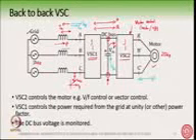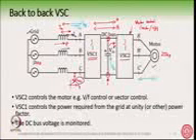So this current, the current which is drawn, this current IA, whatever direction you take, if you reverse the current, how will you reverse the current? You will reverse the current by changing this phasor position with respect to the grid voltage. If you change the position of that phasor, then you will reverse the current. Once you reverse the current, the power will then feed back.